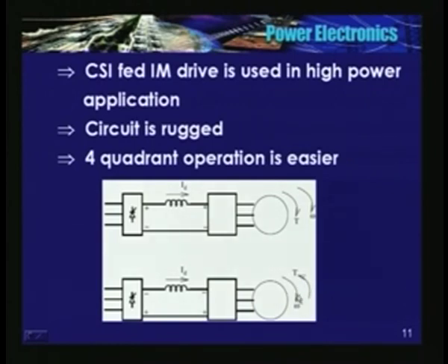Torque and omega. Operation has changed, has gone to another quadrant. So maybe a regenerative braking. Speed will fall. As the speed falls or near the zero speed, you want the motor to rotate in the reverse direction,